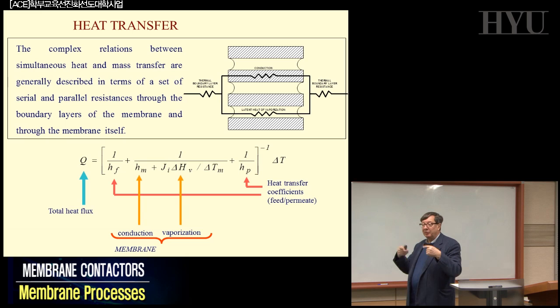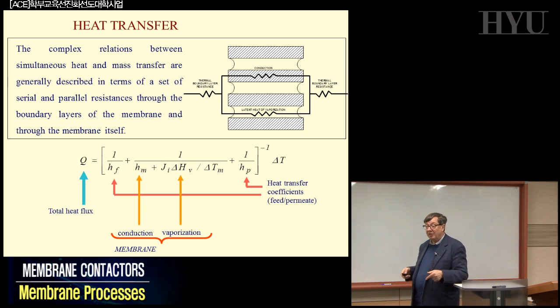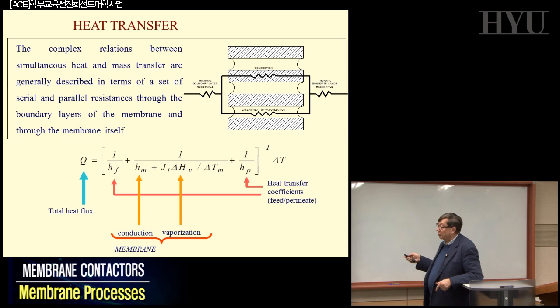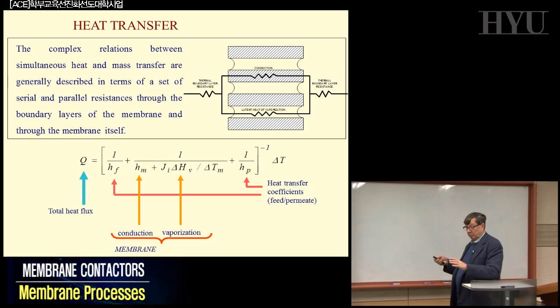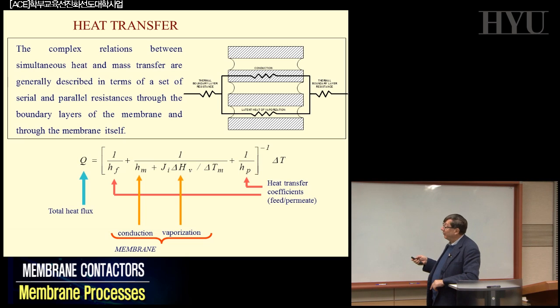So people are working to try to solve this kind of problem, recovering most of the heat you are supplying, inventing new membranes where thermal conductivity has to be very low. That means new materials with very low thermal conductivity, or traditional materials filled with other materials that decrease thermal conductivity, etc., etc. So this is another open field because today 50% of the energy basically is lost.